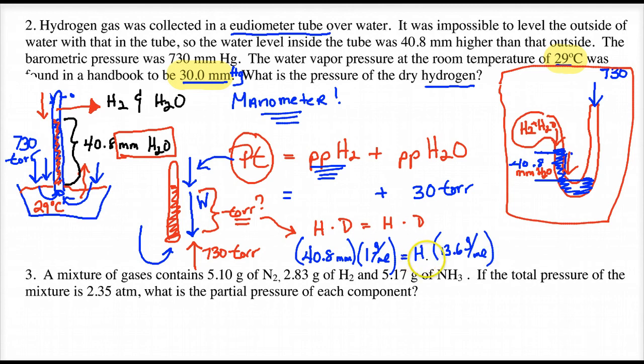And you solve for H, this would go to the bottom, so grams per milliliters would cancel, and you're left with some value that is 13.6 times smaller. That makes sense because the density, okay, is 13.6 times higher.